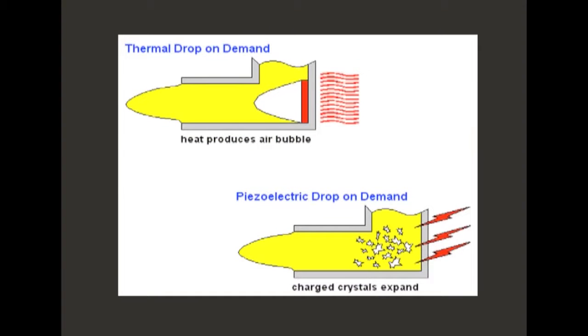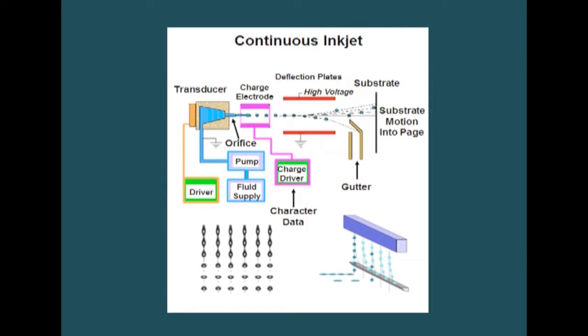DOD piezo uses a permanent print head in contrast to thermal printers. The technology is based on piezo crystals that change shape and squeeze the ink chamber. An electrical charge is applied to the cartridge nozzles and excites a small piezo crystal inside the chamber. The stimulated crystal changes its shape and squeezes the ink chamber, expelling the ink forcefully from the nozzles onto the fabric surface.